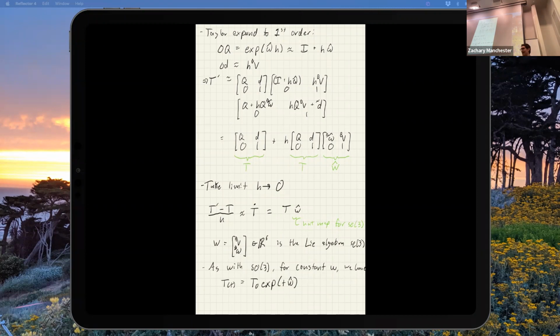The same kind of gymnastics we went through for the rotation-only case, but it turns out you can stuff the velocity in there, and as long as you write it in the body frame and everything's consistent, you can write this whole thing as a group too. It turns out, with fun recent research from about the last 5 years, I mentioned this invariant Kalman filter stuff. You can stuff lots of other things into a matrix like this and keep going and make bigger and bigger groups. And some guys at Michigan had a field day with this recently and came out with a bunch of really nice results for invariant filtering for legged robots.